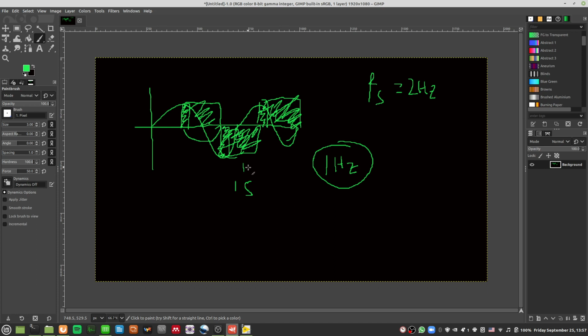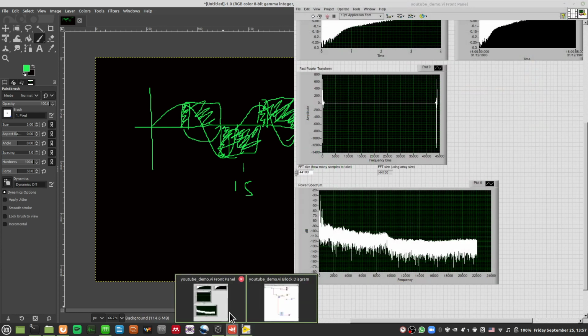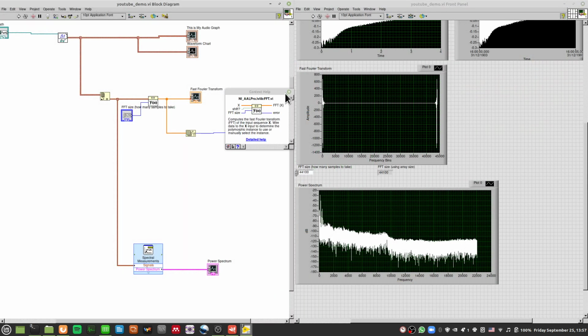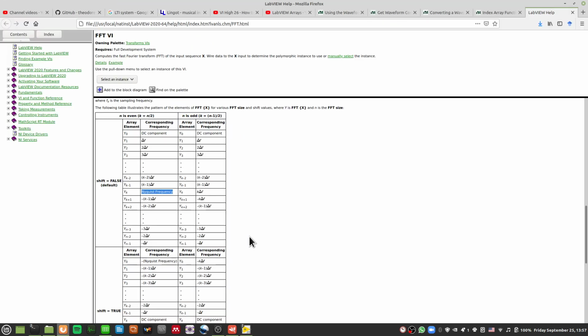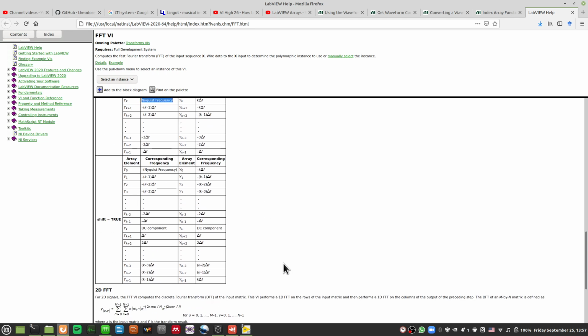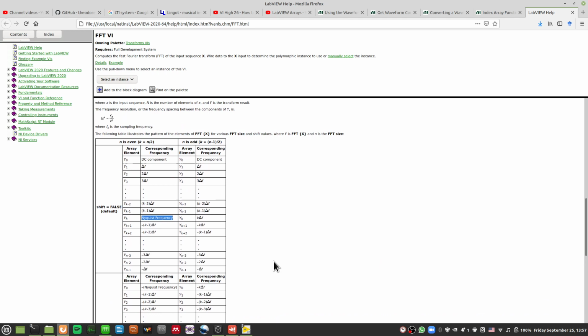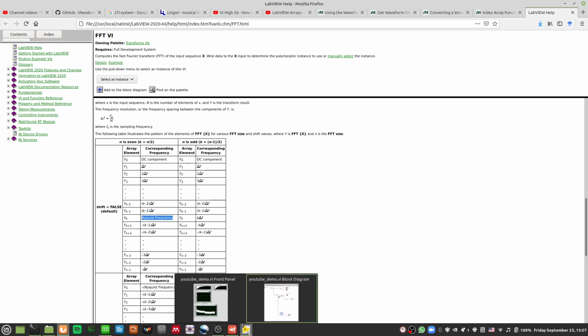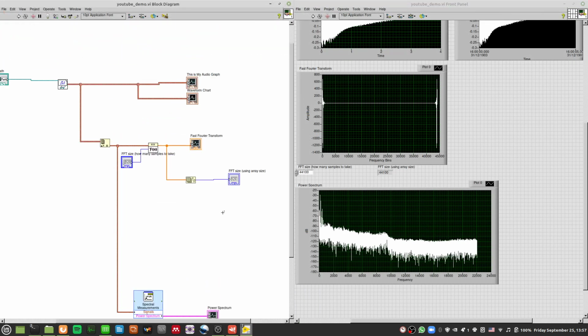So that's why I guess you can say that we can only sample up to 22.05 kilohertz. Anything more than that, you will not be able to sample because of that logic I just roughly gave you. So this is the intuition behind the Nyquist frequency. Okay, so of course, we want to move on and discuss a little bit more about waveforms.